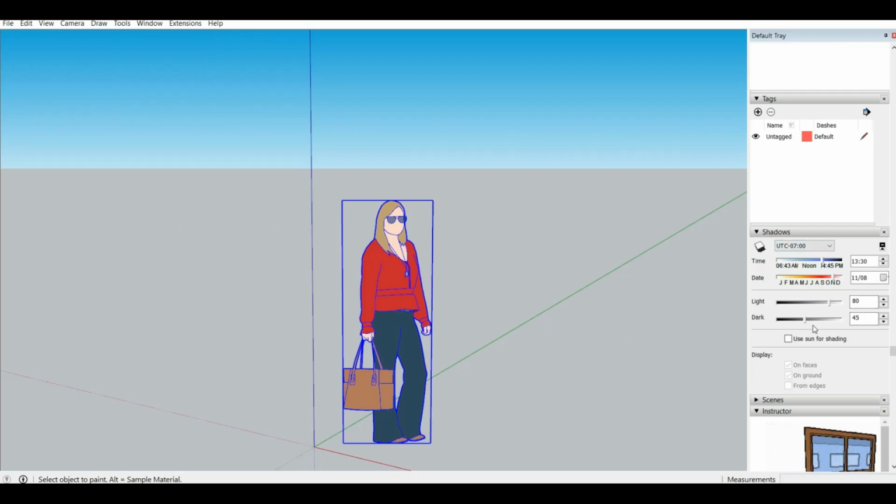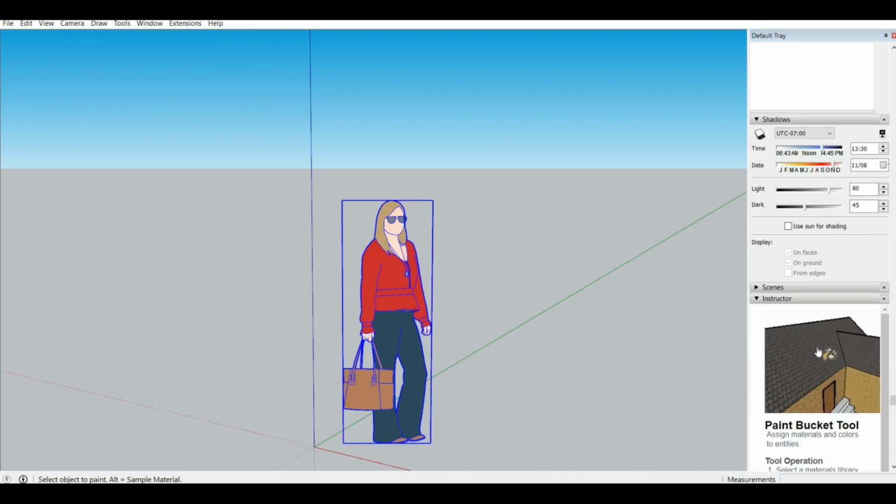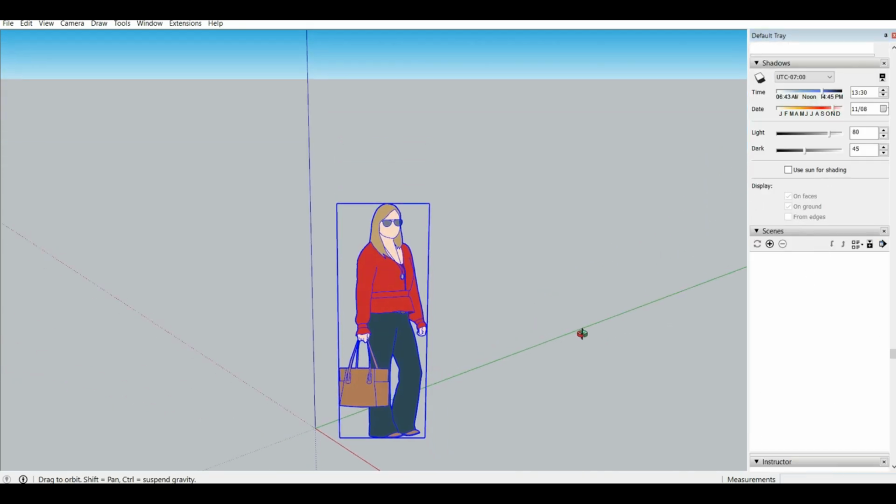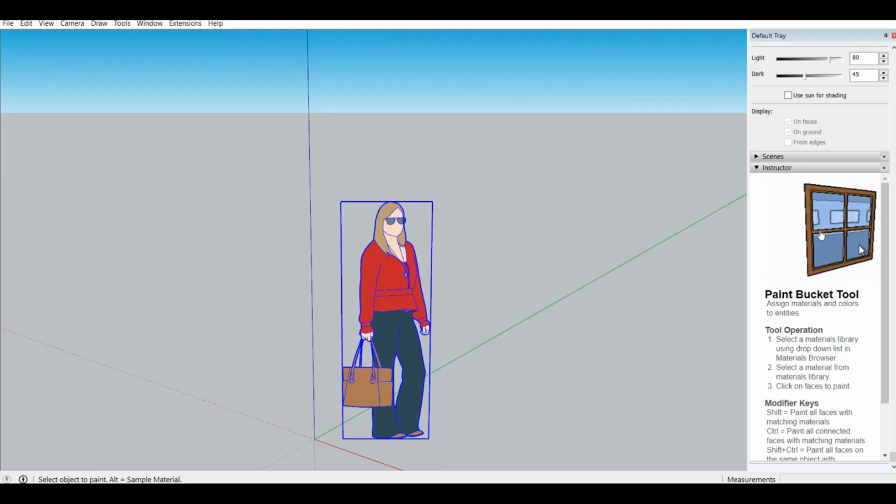So now the shadow pane. With SketchUp's shadow feature, you can make your model cast a basic shadow or see how the sun casts shadow on or around a geolocated model. By default, shadows are turned off because they can use a lot of your computer's processing ability, but from here you can turn them on.